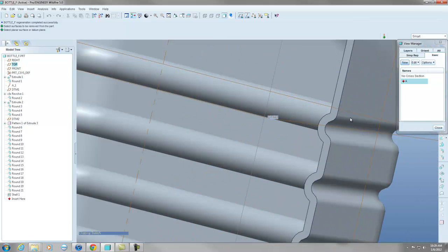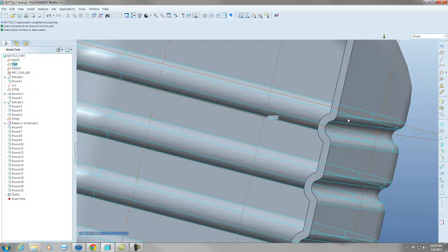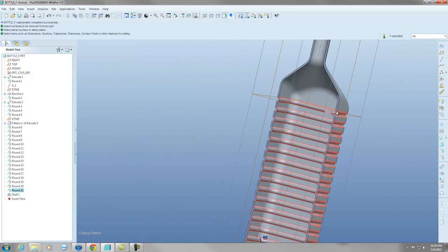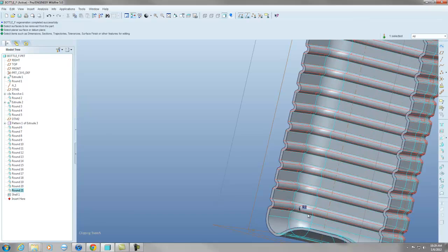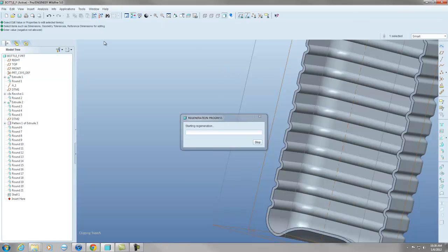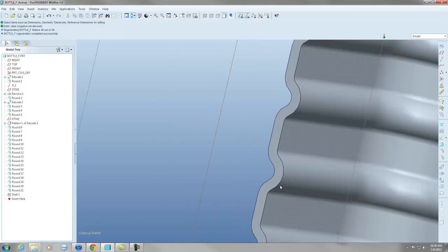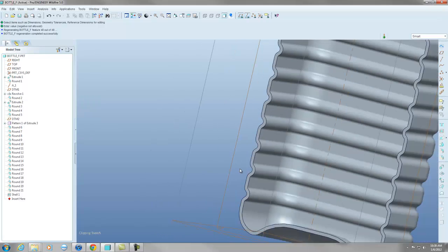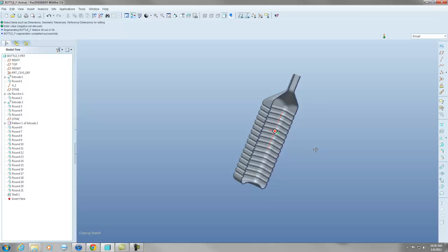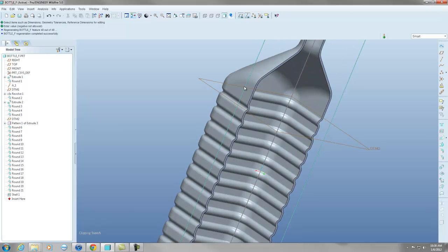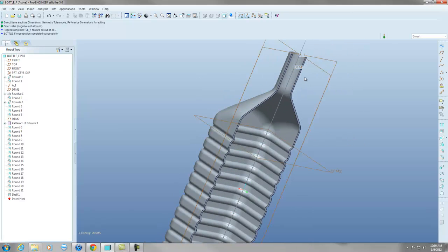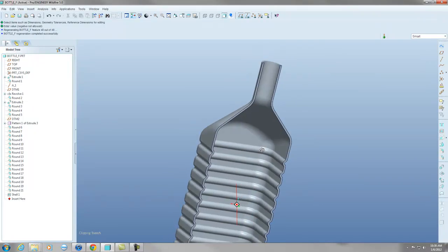Now, obviously, this radius isn't big enough because it's a sharp edge on the inside. So if we make it 3.5, maybe. There we go. Now we get a radius on the inside. Because what it's doing is when you hollow it, it's offsetting this face inside. So, okay.